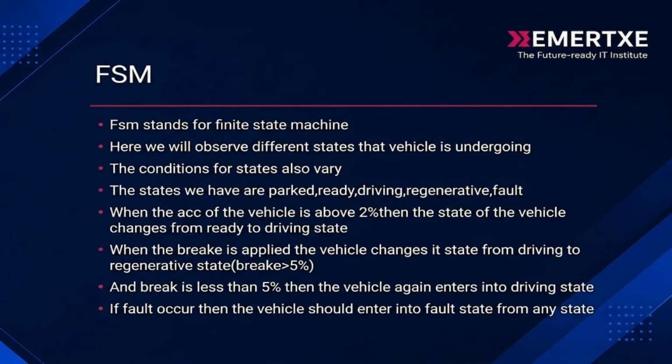When the acceleration of the vehicle is above 2%, the state of the vehicle changes from ready to driving state. When the brake is applied, the vehicle changes its state from driving to regenerative state. Example, brake greater than 5%.